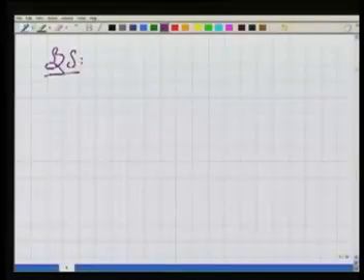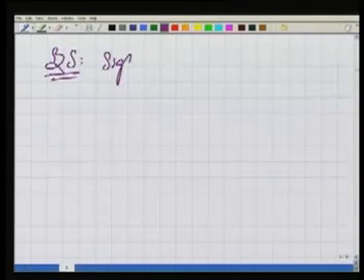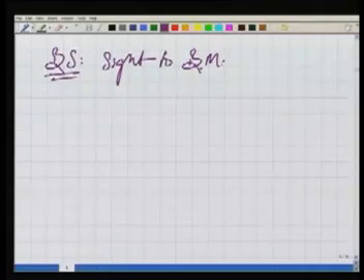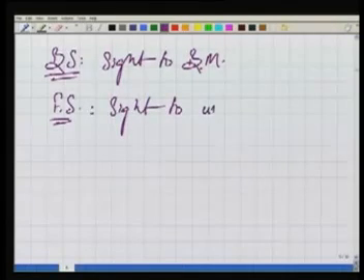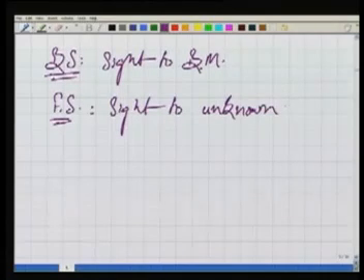So what we are doing in this case, we are trying to make my sight to the known point. Let me also define this. The backsight is a sight to, I can say, benchmark. Benchmark means something for which we know the elevation. It could be a known point. And foresight is a sight to unknown. We do not know the elevation.